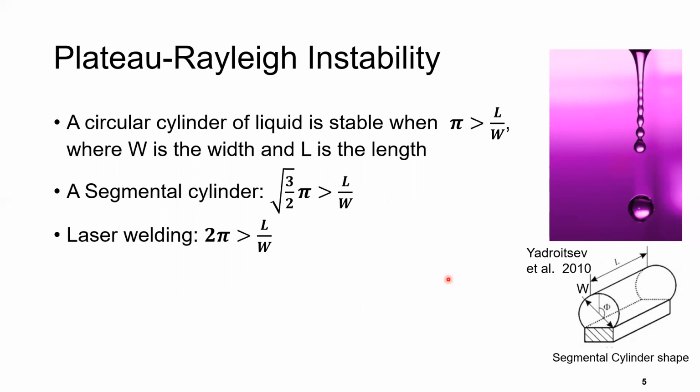So what we can take away from this is that there's clearly not a great consensus here about what this critical number should be. However, there seems to be a general consensus that this ratio of the length of the jet, which translates to melt pool length roughly in our scenario, and melt pool width is important in governing this phenomenon. So there, the instability is kind of boxed in for you.